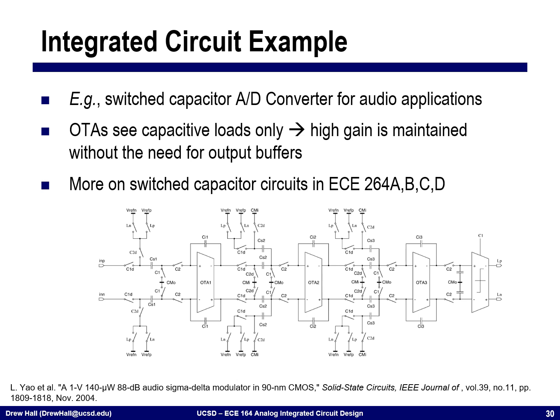All right, so now I want to walk through a couple of examples to show you how you might actually use these OTAs in much larger structures. What I'm showing you here is an analog to digital converter for an audio application. This is what's called a sigma delta modulator. It's essentially a cascade of integrators and then a comparator back here at the end with feedback around it in order to drive these switches back here at the inputs in order to balance out and stabilize the system.